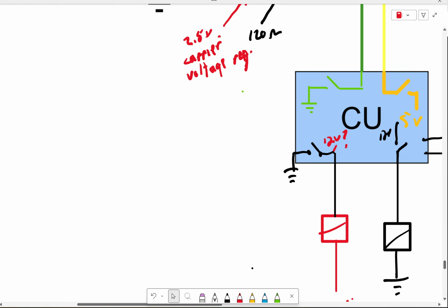Sometimes a controller, whether it's an engine controller, maybe a hydraulic system controller, actually has its own separate sub-network that it communicates with. Okay? A good example of that for an engine controller would be your after-treatment system. A lot of your after-treatment system sensors and even the DEF system on it, that's all running on kind of a secondary CAN bus, right?